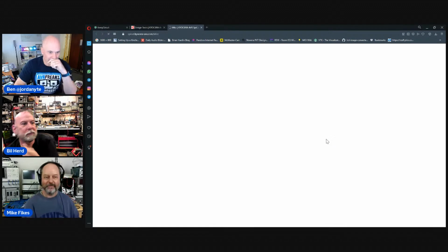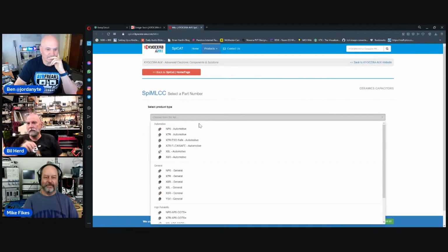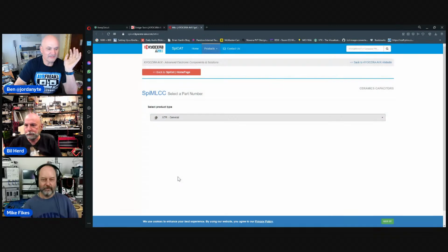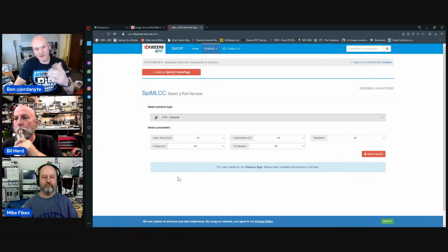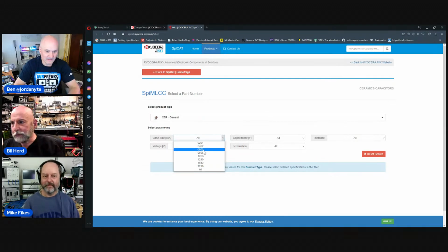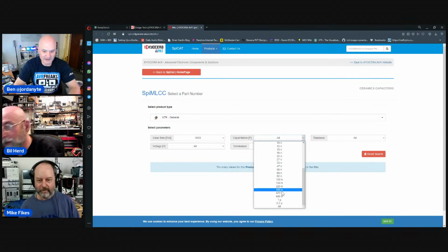So these are very cool tools because, let's go for a regular X7R, let's say general purpose X7R. So we all say, I'll use X7R caps for decoupling your digital boards, and I'm going to go with 0603. So these are our popcorn components, right?